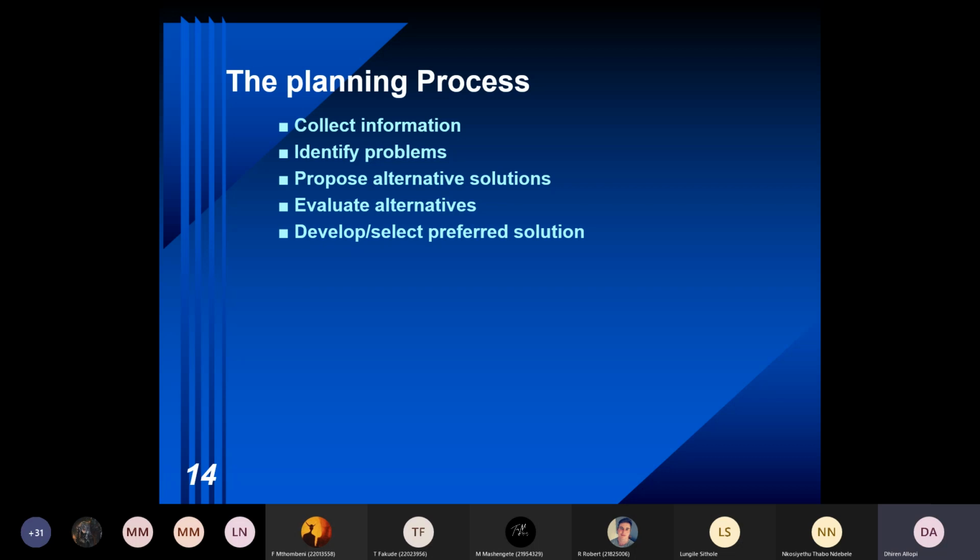Now, I use the word capacity again, and I'm sure it's not a terminology that you haven't come across. Capacity is the maximum number of vehicles passing a point per hour. Normally it's per given time, per hour. So any traffic engineer's goal is to achieve maximum capacity. So how do you do that? You've had a look at various factors that affect capacity, like your road width, your shoulder width, potholes, geometric restrictions, sharp curves, poor sight distance. You've covered all those aspects.